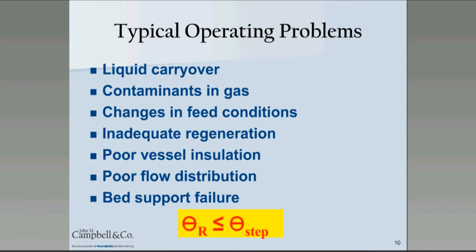Contaminants in the feed or in the regeneration gas are a big issue. Air dryers, for instance, can last decades because the gas is very clean. Some contaminants will coadsorb during adsorption and increase the mass transfer zone. This can lead to a larger than anticipated reduction in the adsorption cycle. Some contaminants can react with the binder of the molecular sieve and destroy its structural integrity. Amines can do this, so can salt water. Let your sieve vendor know what contaminants are expected in the inlet gas so they can recommend the appropriate action to take.